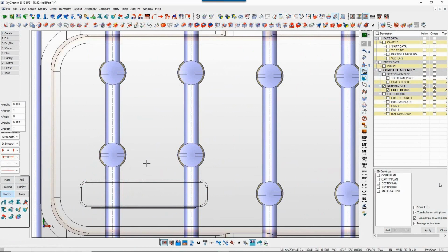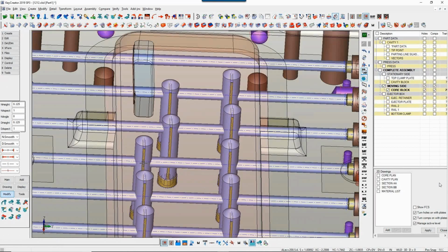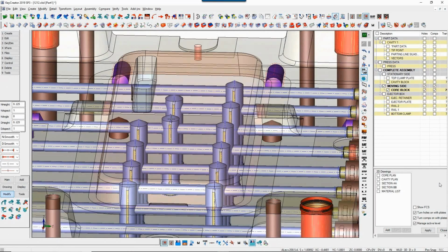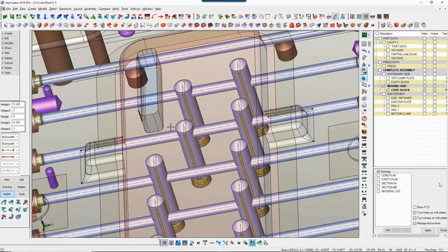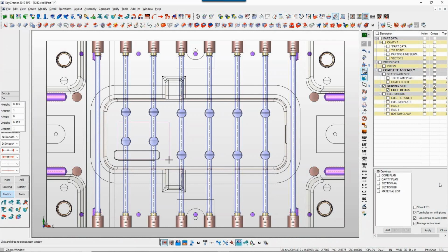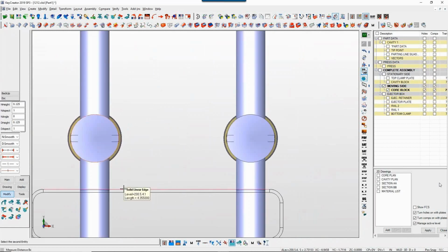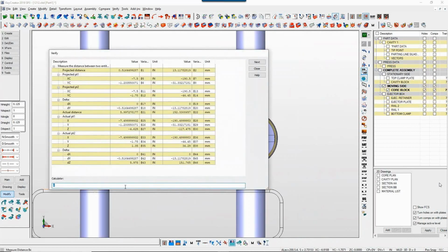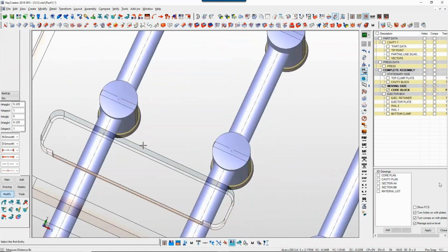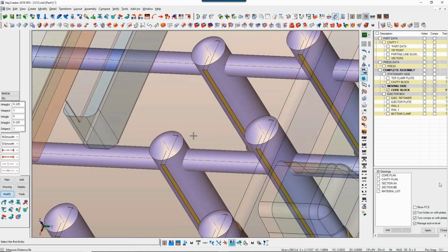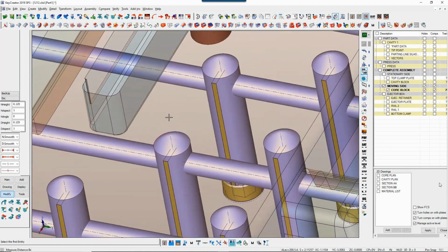Okay. All right. So what you can see is they've moved and it made them a little bit taller, okay? But they still didn't go to the height we want. The reason being is that 3/4 inch value that I have it configured for, right? So what it's seeing is the sidewall of this baffle to the sidewall of the insert is just over 1/2 inch, right? Right here, 5/16. So because of that, it's not going any taller because it's staying that 3/4 inch away from that pocket.